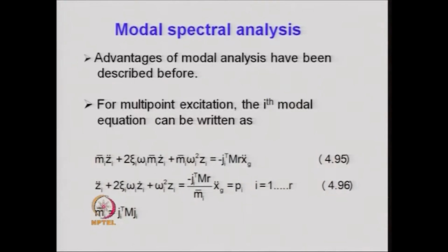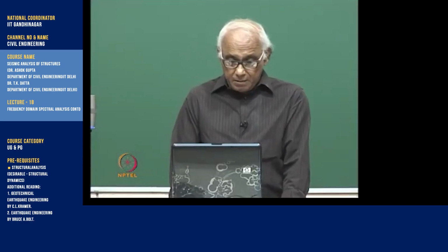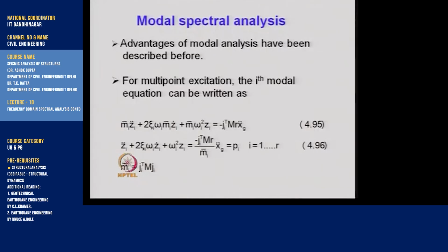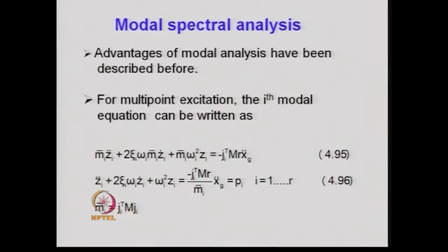Now, since we use the mode superposition technique to uncouple the different equations of motion of a multi-degree freedom system and simplify the problem, that is, a multi-degree freedom problem can be converted to a set of single degree freedom problems, and for each single degree freedom problem one can obtain the responses in the generalized coordinate, and from there one can obtain the displacement in the structural coordinate using the mode shapes.